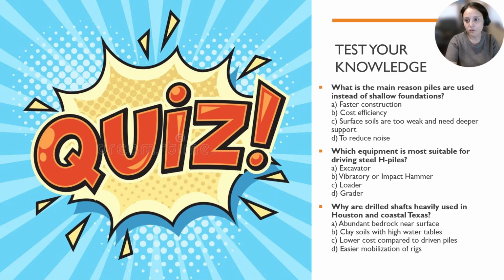All right, quick check before we close. First question: what is the main reason piles are used instead of shallow foundations? Because surface soils are weak and we need deeper support. Which equipment is most suitable for driving steel H piles? Vibratory or impact hammer? Why are drilled shafts heavily used in Houston and coastal Texas? Due to clay soils and high water tables.